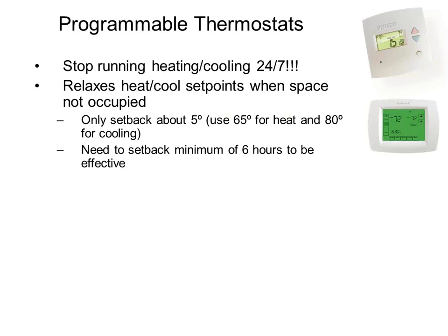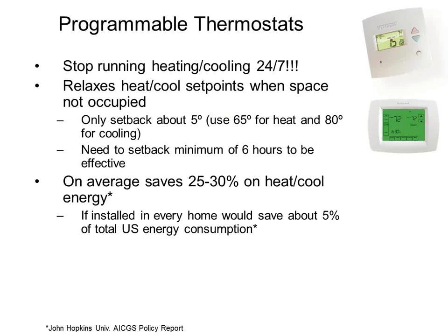So if I don't do it for a very long time frame, I don't get a lot of run hours with that reduced temperature differential across the wall. If you're not doing it for at least 6 hours, you're probably not going to see a substantial savings. Plus, I would say that minimal savings from doing it for shorter hours is really just a training issue. If I have to keep showing someone how to program their stat, and all I'm going to save is a few bucks a year, it's not worth my time. But if they can set it back for 6, 8, 10 hours a day, then I can get some decent savings out of it. Those are just my rules of thumb, based on watching hundreds of buildings as a controls guy.